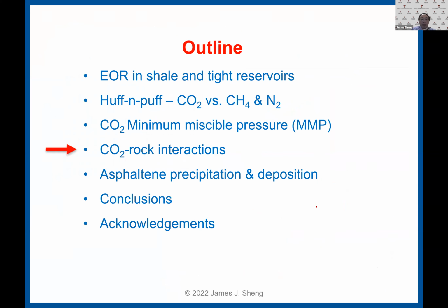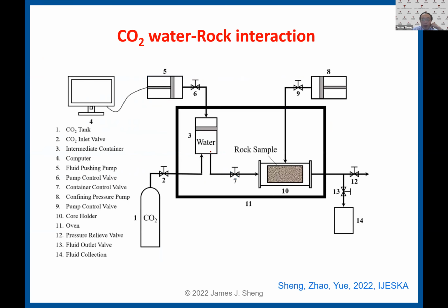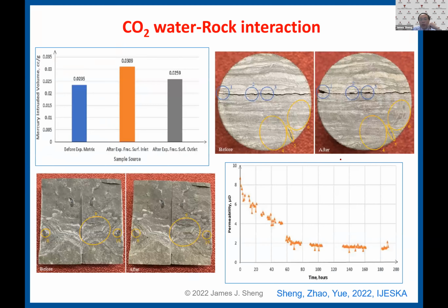Okay. Next, I'm going to talk about CO2-rock interactions. What we did is, here is the core, and this is a water tank. CO2 goes through the water and is saturated, so this is the CO2 solution, and then you inject it through this rock. We inject at a constant rate and measure the injection pressure.